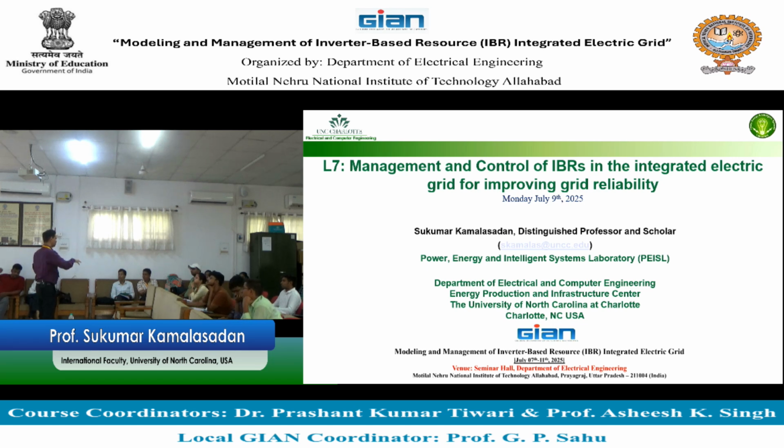So we divide the assets, PV farms and battery, into two: one is a controllable asset, another is a non-controllable asset. The non-controllable asset pushes active power, whatever it produces. The controllable asset is in the form of, for example, energy storage. Now, this controllable asset is money. You need to find when, how much to size, where to put it, and how many to put.